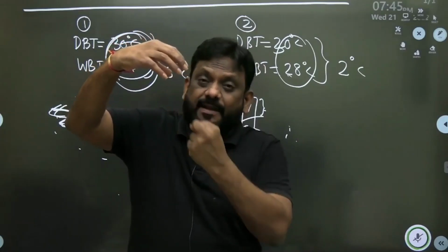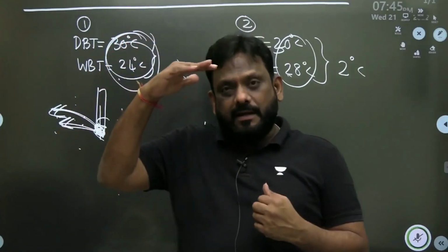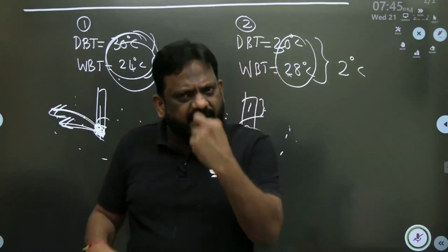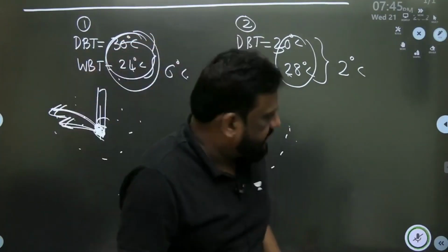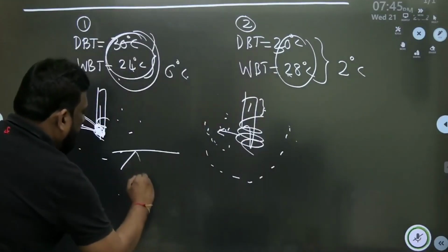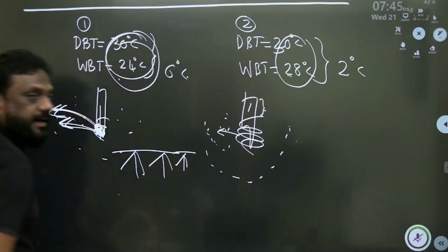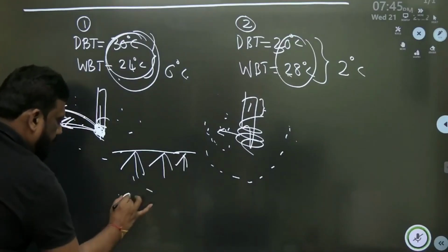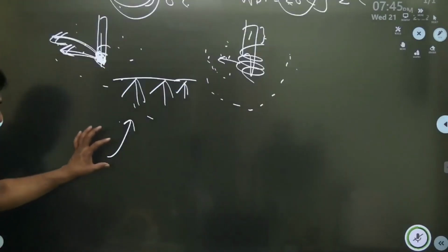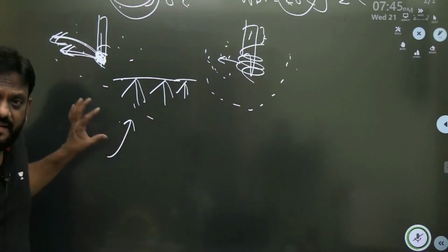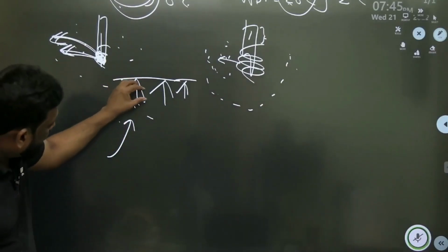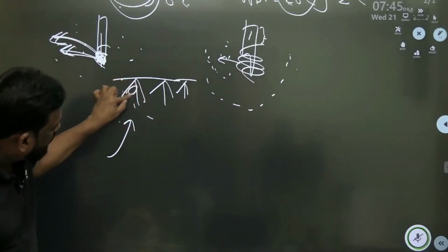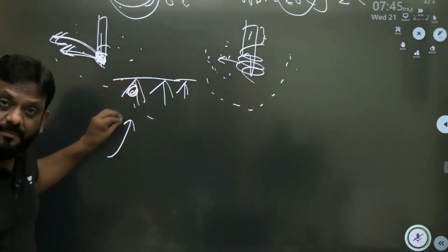So therefore, air temperature is coming down. I repeat, sirs, water is trickled like this in cooling towers. Now, water is sprayed like this, and when water is sprayed, air is flowing. Look, my dear students. If the moisture in air is less, it will absorb moisture, and when it absorbs moisture, it has to take heat from this water. So thereby water temperature will come down.